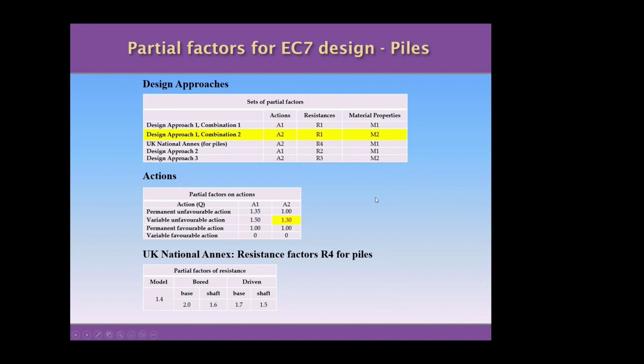In terms of the Eurocode, what we're going to need is the same thing we have been using for shallow foundations, walls and slope stability as well. So, following the advice of Eurocode 7, we are going to use Design Approach 1 Combination 2. So we are going to use the columns of the subsequent tables as indicated in this table in here.